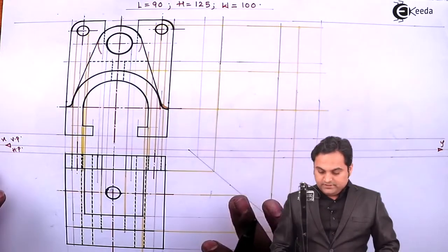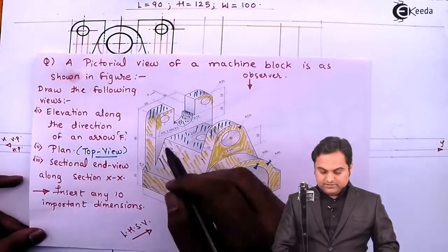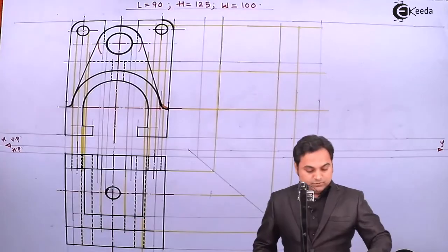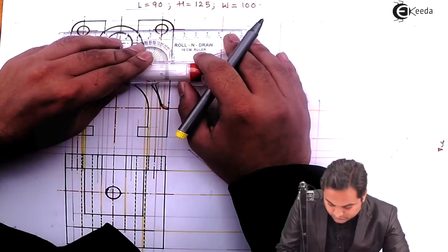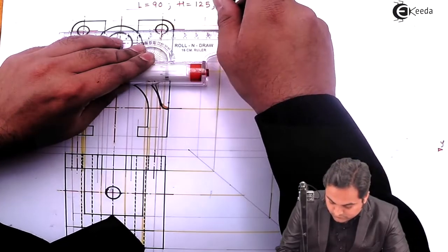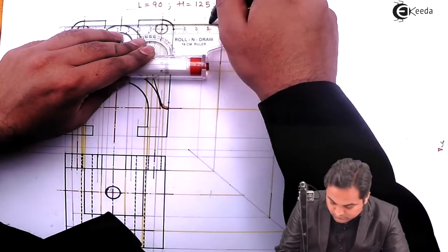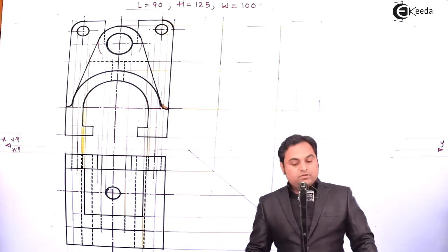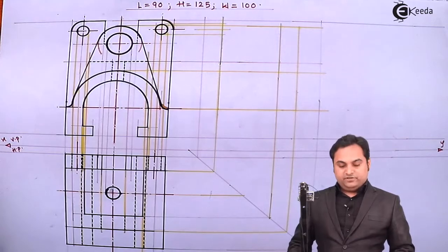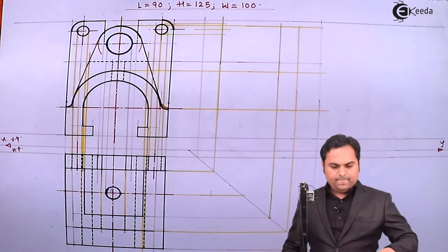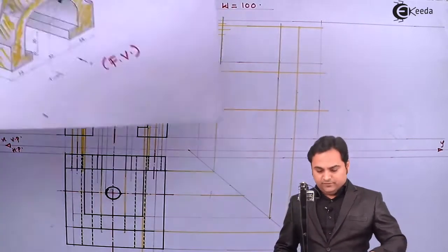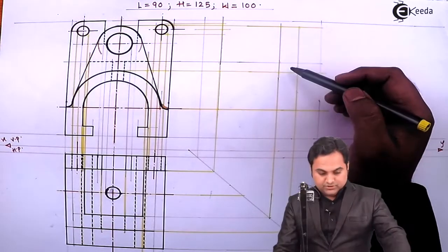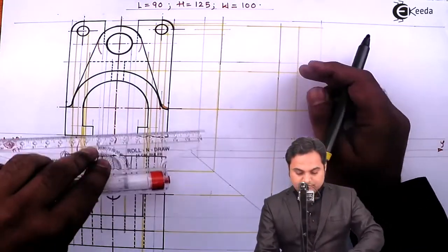Next, after reaching up till here, there is a circle inside this plate. So getting it from the front view, projecting its center. So this circle will be hidden here if I'm drawing the plain side view. Another circle inside this disc, which is here, I'll get it from the front view.